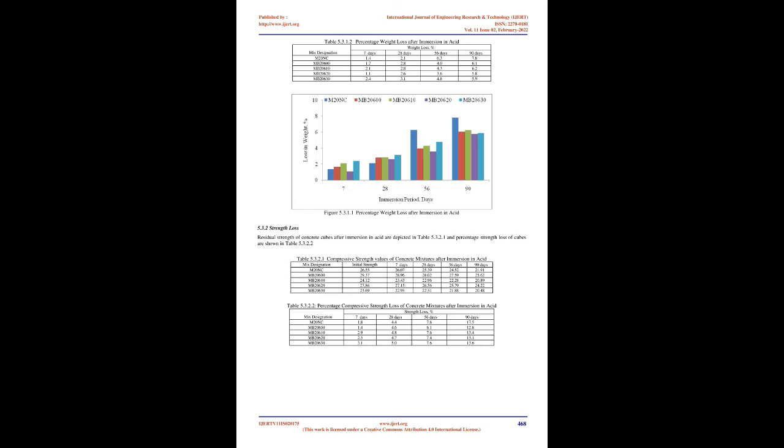4.1 Compressive Strength Test. In the present investigation, compressive strength is determined as per the procedure given in IS 516:1959. Compressive strength is determined on 150 x 150 mm³ specimens using UTM at a loading rate of 140 kg/cm²/min.